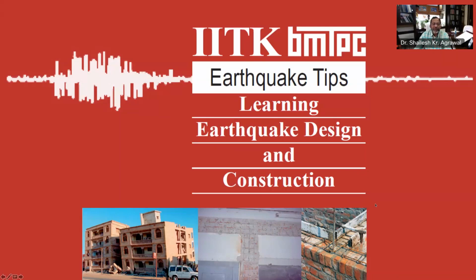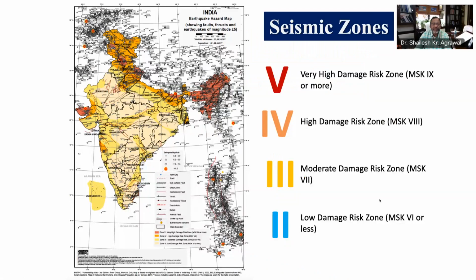Let me first introduce these tips to you, but before that, look at this map and remember it for your lifetime. This is the seismic or earthquake zoning map of our country published by the Bureau of Indian Standards, and it is mandatory on our part to look at the seismic zone of the place and incorporate design and construction measures as per zoning for the facilities we are developing at that particular location.